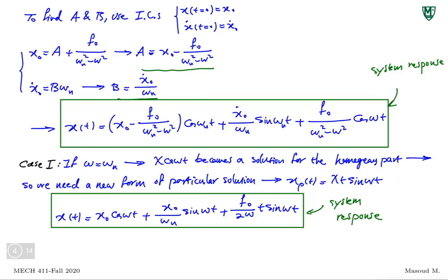And if you want to think about the structure, it breaks. Like if I have a column that I'm going to excite, or a specific part of a machine, if it is being excited at its natural frequency, the amplitude increases a lot. In this case, we don't have damping, so it goes to infinity. But at some point, this increase in amplitude is going to break the system.